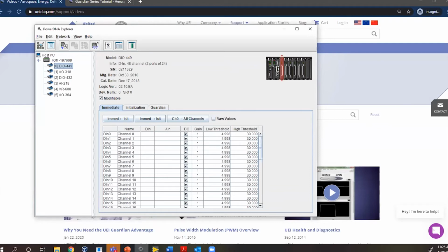Whether someone is being trained to work on a helicopter, a plane, or anything else, you're going to have different voltage levels for signals. They could be 5 volts TTL, 10, 12, 28 volts. And when you talk about avionics, you're also going to see 400 hertz AC signals.